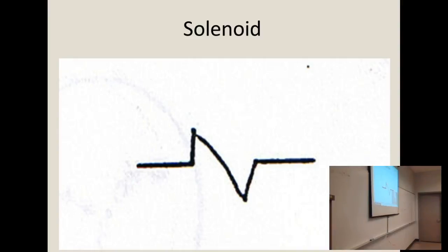That's a gas valve. This regulates gas to the furnace. In other words, it opens, it shuts. When I want heat on, it opens up. I don't want gas flowing all the time. Shuts. So there is a solenoid.